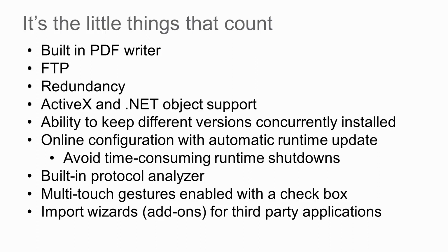There are built-in troubleshooting tools such as a built-in protocol analyzer. You can view the actual bits and bytes that are going across, protocol-wise, very similar to what you might see in a Wireshark type product, right in the product, so you can analyze your communications and see what's going on.